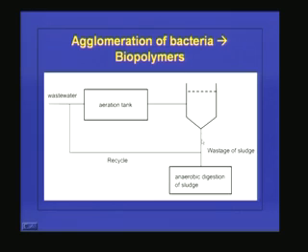So here settling will be taking place because a lot of extra sludge will be generated, and from here we will be getting clear effluent. A portion of the sludge will be wasted, that will be going to the anaerobic sludge digester, and a portion will be recycled to the aeration tank to maintain a constant biomass concentration in the system, because we have to provide more and more workers, then only the process will be efficient. So the purpose of recycling in the activated sludge process is to increase the biomass concentration in the aeration tank.